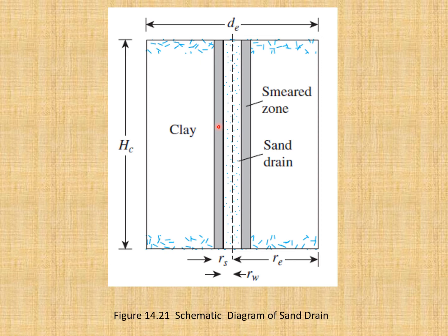And one more thing that you must keep in mind for the smeared zone is that it also depends on the method of installation. Dynamic driving creates more disturbance of the soil than static pushing.